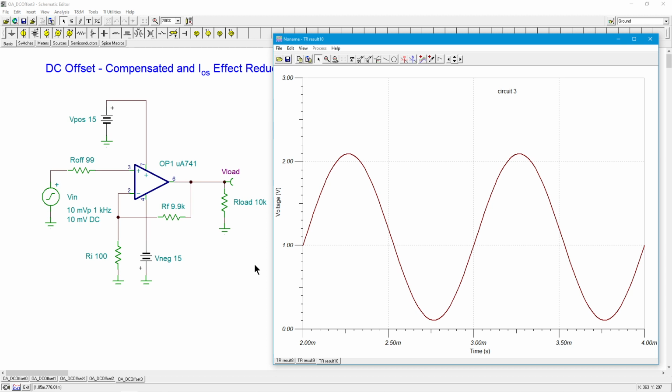What is that reason? Well, this goes back to the simulator itself. If you built these circuits in lab, like you got 10 op amps, you got 10 741s, you build up these circuits, every single one's going to have a different offset. Some of them are going to be positive, some negative, some pretty small, some a little bit bigger. Because again, we don't really know what the matching is. The manufacturer can only give us a range. They can only tell us, hey, it's going to be around here. Worst case, it's going to be this much. But somewhere in there is where it lies. It's a statistical occurrence, a probability in terms of what you're going to get.